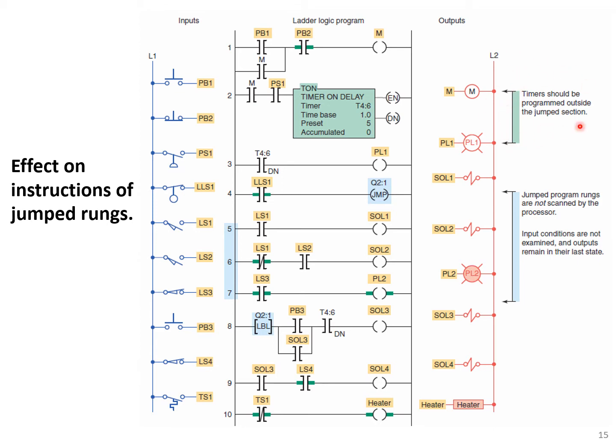Here we have a nice point. Timers should be programmed outside the jump section. We should always put timers outside the jump section, because when it jumps, it will affect the performance of the timer, and the timer doesn't work properly.